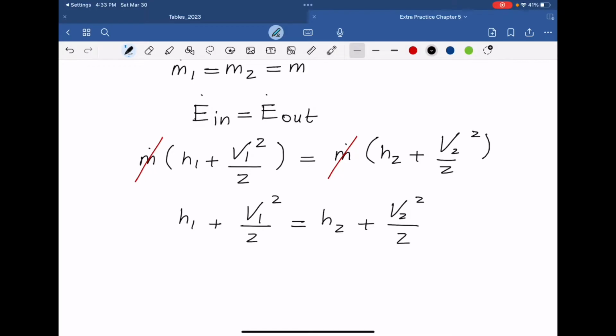You can directly solve this equation for V2 and do a calculation, or other arrangements of this equation are also fine as long as you know what you're looking for. So I'm going to arrange it in this manner and solve it for V2. And then we also have to remember something very important, the unity conversion ratio that we need to use here, because the kinetic energy unit is meters squared per second squared, but we need to convert that to kilojoule per kilogram. Let's not forget that.